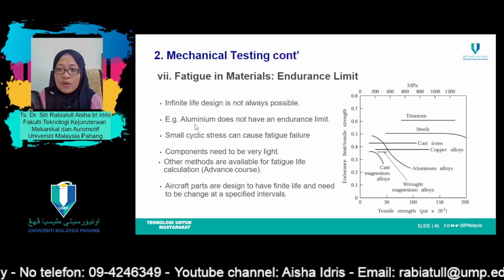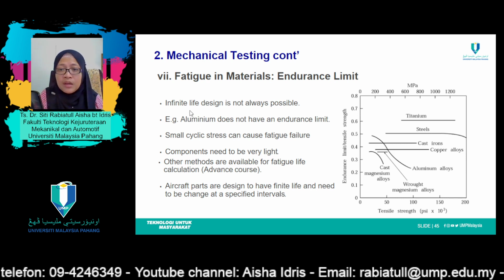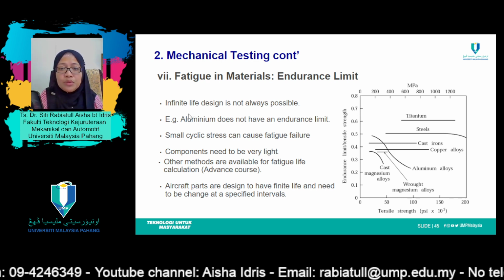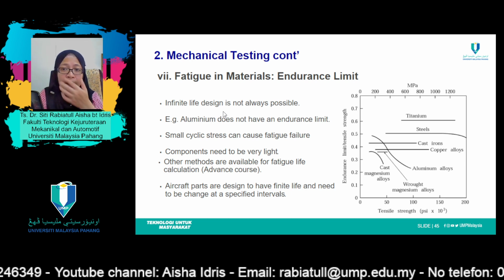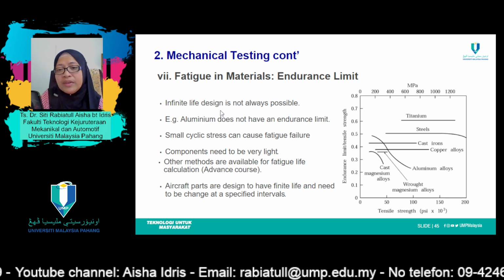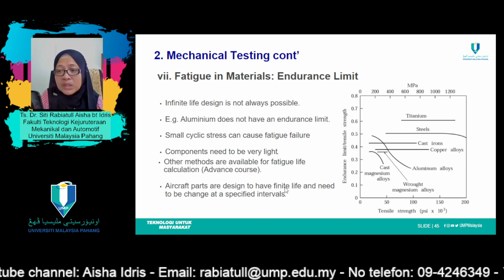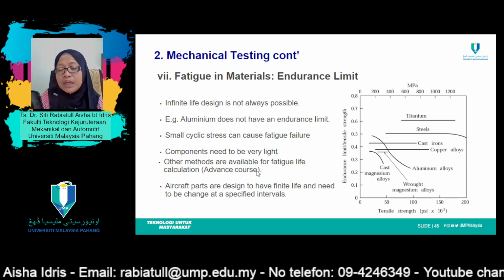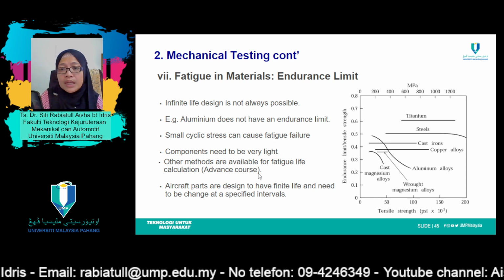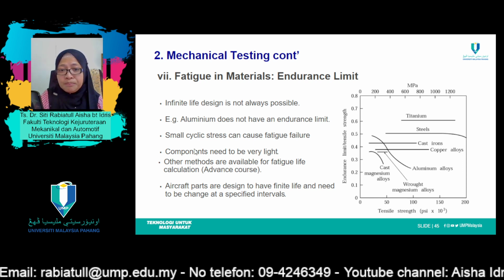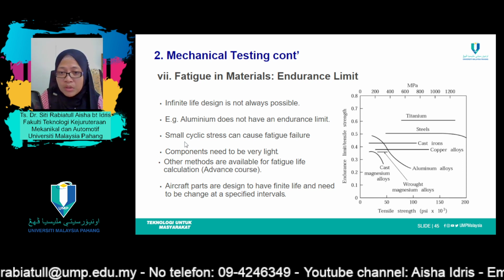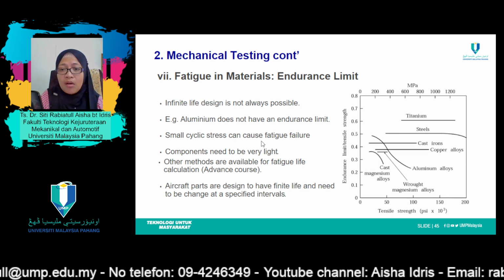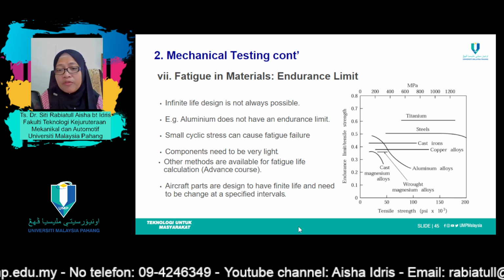And the endurance limit actually refers to infinite life design. This infinite life design is not always possible for any type of material. For example, aluminum just now does not have an endurance limit, and therefore small cyclic stress can cause fatigue failure for these types of materials.